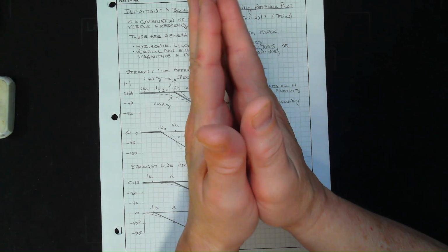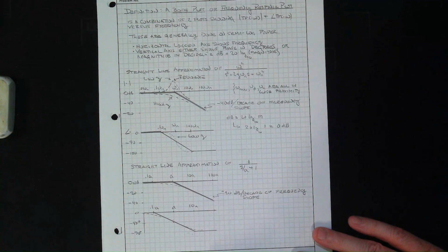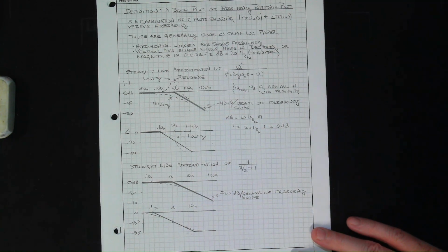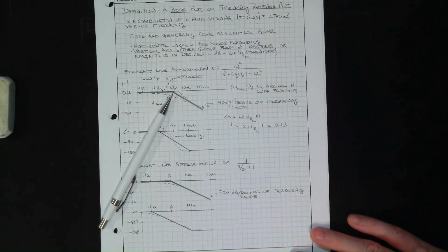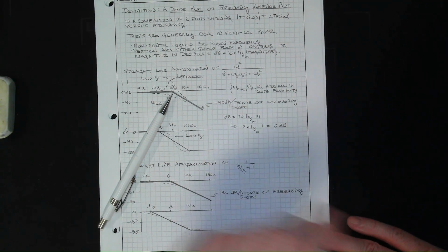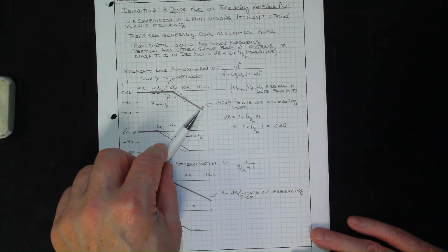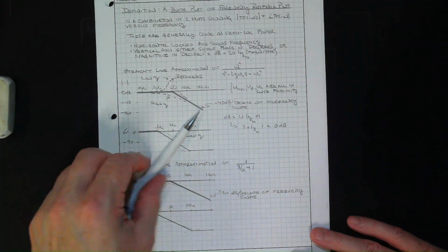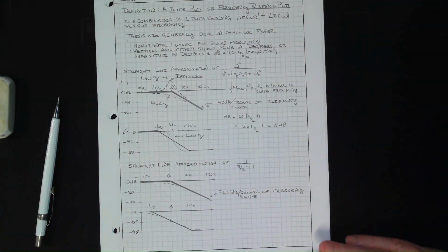And that is a natural phenomenon of low pass systems. Once you get up to your maximum velocity, the only way you can keep up with the frequency of going back and forth, because you have to maintain your frequency, is to cut your amplitude. It's the only way. So when you start seeing this falling off, the machine is telling you, I can't go any faster. And so it starts cutting off amplitude to maintain the frequency, which it has to match. So that's what we're seeing.